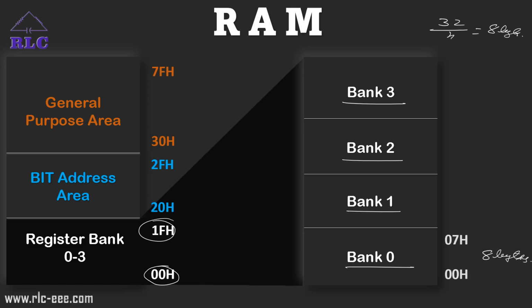These bank addresses are 00H to 07H for bank 0, 08H to 0FH for bank 1, 10H to 17H for bank 2, and 18H to 1FH for bank 3.